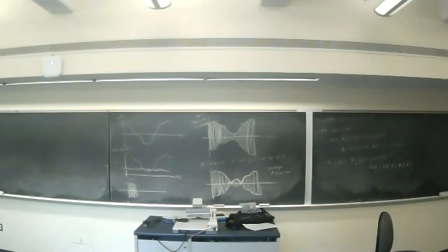So if this were speech signal, W here would be about 4 kilohertz. Okay. The telephone company assumes that the signals they send over the telephone lines are no higher than 4 kilohertz. So that's why you can't play music over the telephone. It just doesn't sound good at the receiver. All the high frequencies are gone. Okay, so for speech, it's about 4 kilohertz. If you're going to use this for music, you'd need this to go up to about 12 or 15 kilohertz for the bandwidth. Okay. So what does S of F look like?